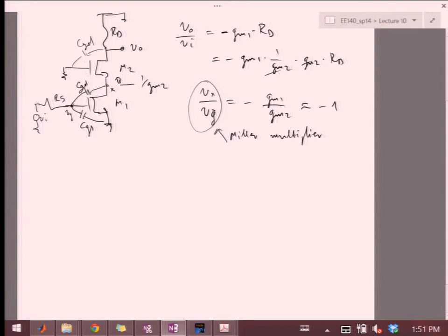And then also, at the exit, in the second stage, I'm using the amplifier that inherently has a much wider bandwidth, which is the common gate. So that's the benefit, or the beauty, of the cascode amplifier, right? By cascading these two and not having the voltage gain in the first stage, I improve the input bandwidth, and then I also improve the output bandwidth.